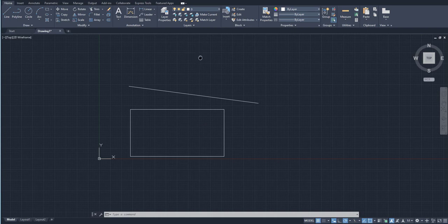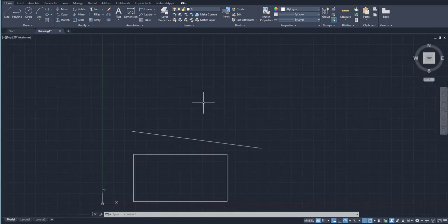For now I'm going to teach you how to draw a line with a specific direction and dimension. I'm just going to move the workspace a little down to create more space, and I just click on the command line. Now it's asking me to specify the first point again. I don't have a place where I'll start the line, so I'll just pick a point randomly, for example here, and just above it you can see a dimension is written 1617.5458. This is the dimension of this line presently.